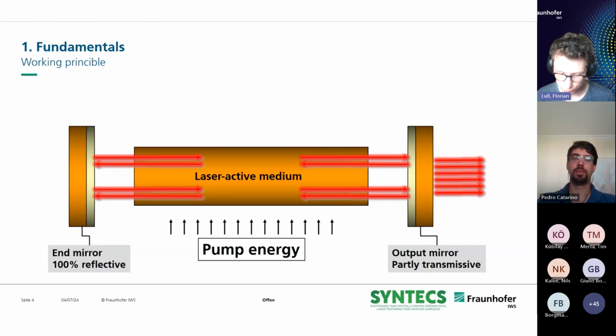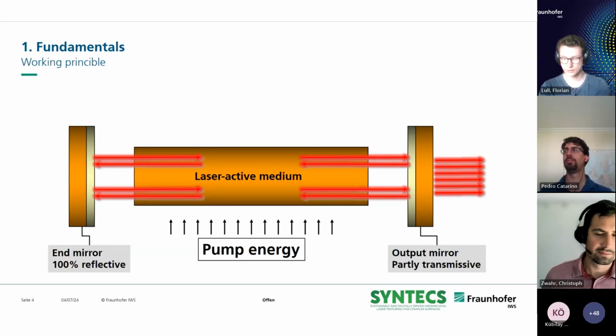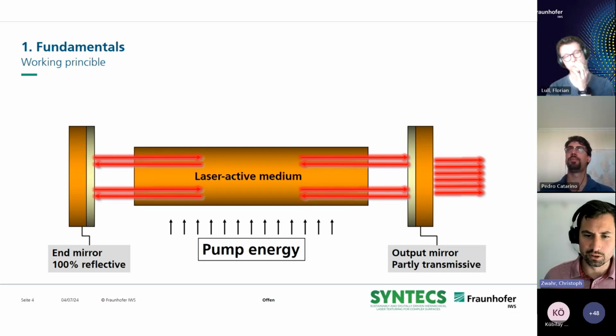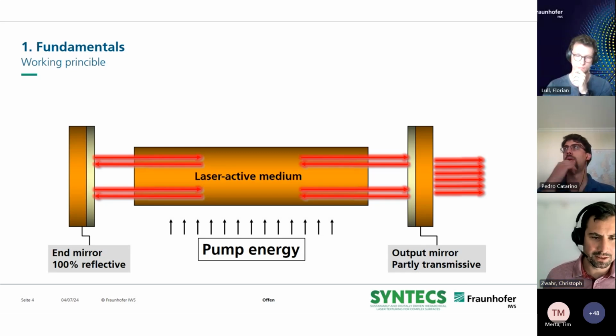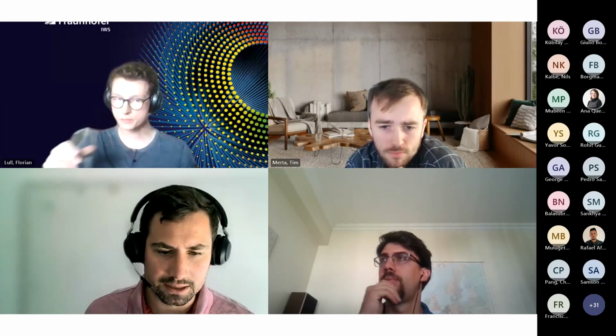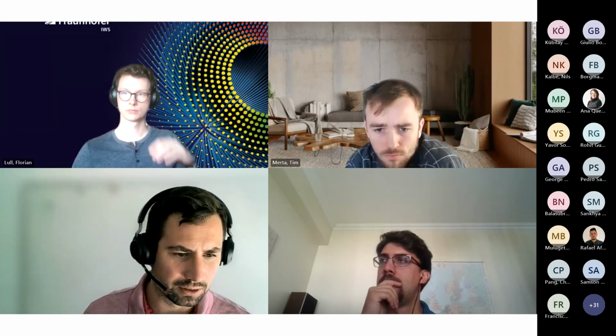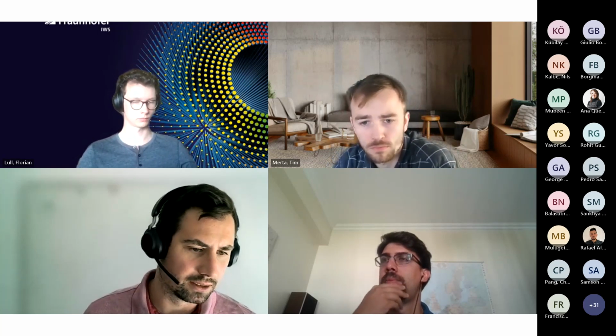I think maybe Christoph can answer this question better. My work is not focused on DLIP, I'm more on direct laser writing. Christoph, can you say something? Yes, Florian. Basically it's possible. It depends on what you call holographic patterning. But if it's just about diffracting light and giving you some light diffractive imaging, that's basically possible, and you can play around also with a contrast for this light diffraction. By changing the size of the interference pattern in each pixel, let's say, you can also give it some contrast. I don't have an example here now, but if you check on our website, you can find some holographic textures that we produced on stainless steel, for example.